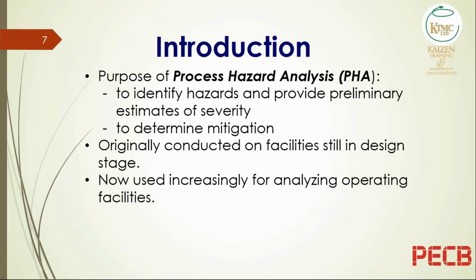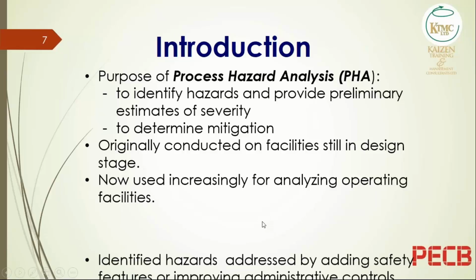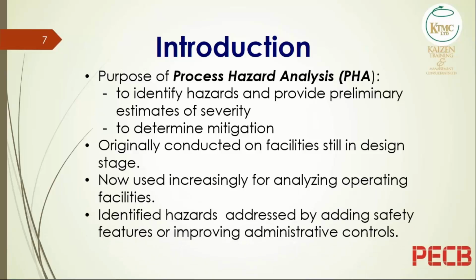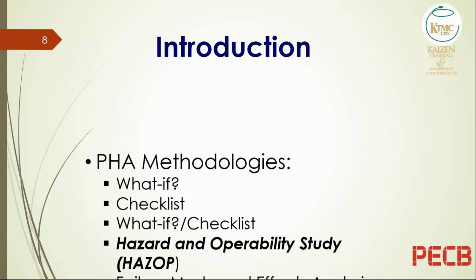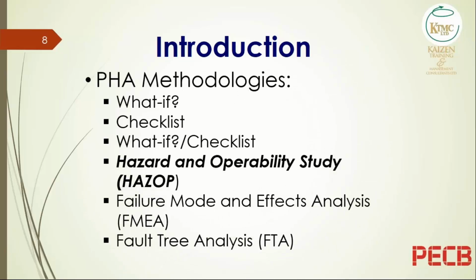It's now used increasingly in analyzing operating facilities, so that's PHA used in ongoing operations, not just at the design stage. It enables the identification of hazards, and these are addressed in order to ensure that they are properly controlled. The PHA methodologies are several. There's the what if, the checklist, the what if checklist combination, and of course hazard and operability studies. We also use failure mode and effect analysis, FMEA, or the fault tree analysis.